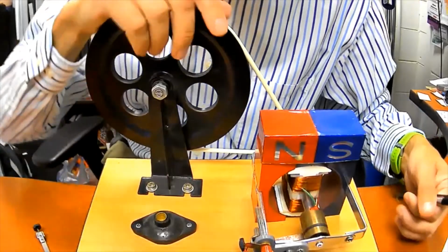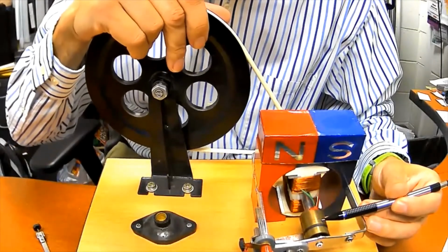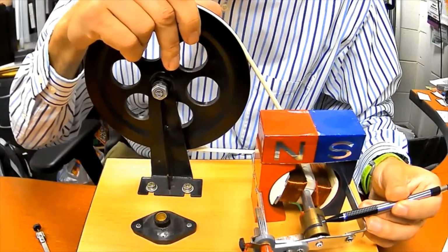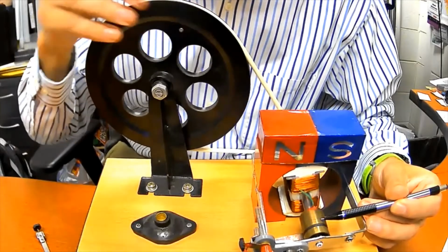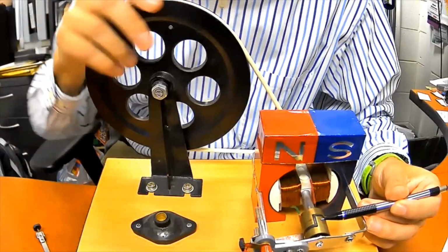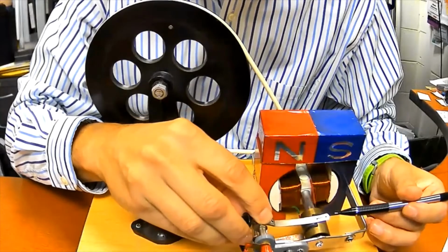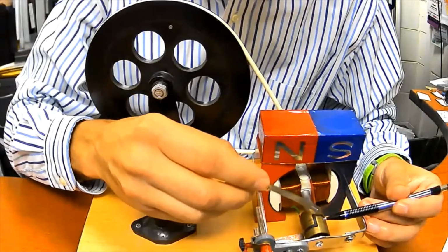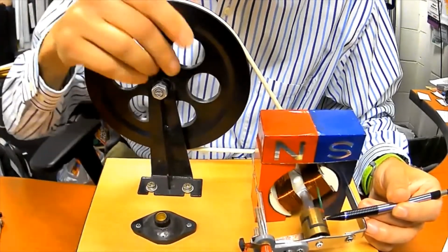But if I put the brushes in the middle, like right here, then what's going to happen is as this rotates, it changes which side the brush is connected to. So right here, it's connected to one side of the split ring commutator, and as it rotates, it changes which section it's connected to. So if I have the brushes in the middle of this device, like right there, then it would function like a DC generator because this is functioning like a split ring commutator. So that's a pretty cool design.